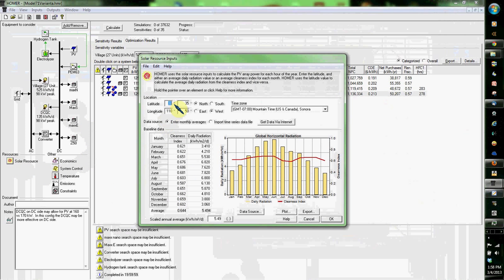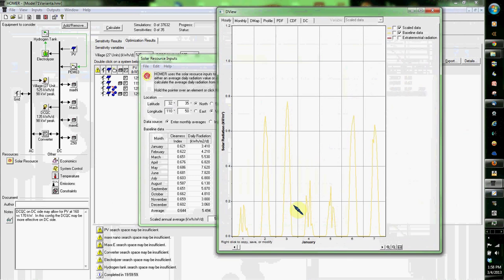Over here, in case I can go into this, I chose locations, and I was able to pull in the data for the solar here at the location 5.4. Make sure you understand your coordinates, because there's a couple of versions of this out here. I flipped out because I grabbed the other coordinates, just double checking at the last moment before my defense, and suddenly my designs weren't working. But it's because I had a different version of the coordinates, so it was actually pointing to a different location. Spare yourself a heart attack and avoid that.